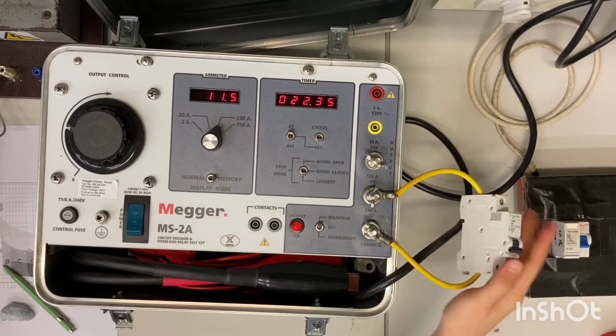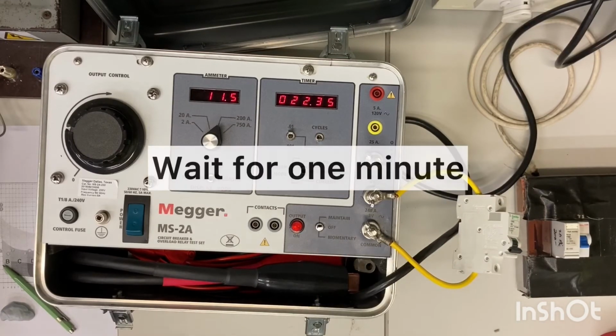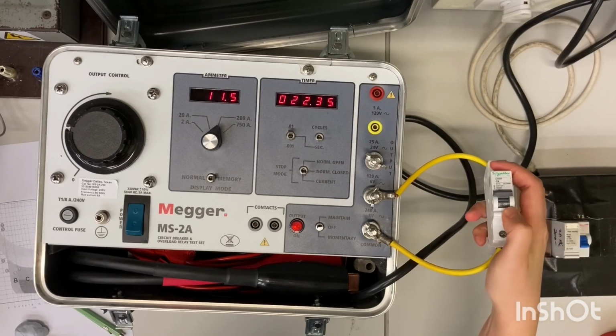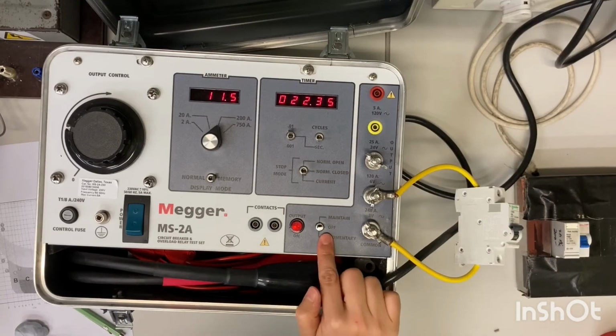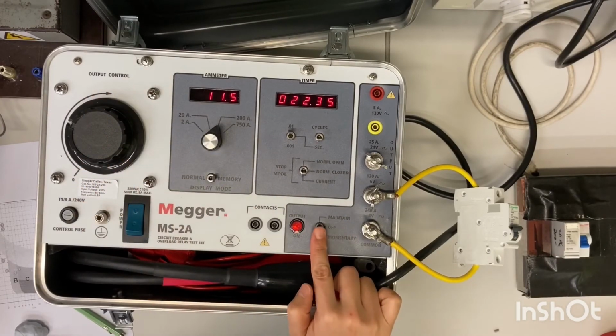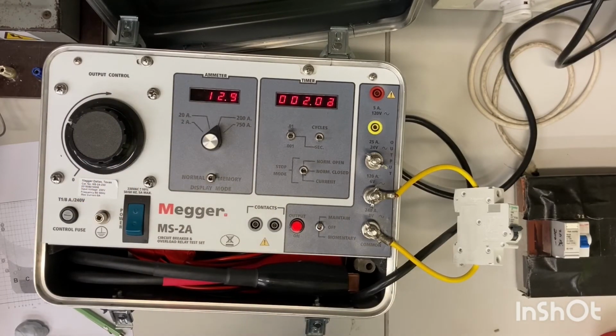So we just heard the click sound. The MCB is tripped back to the off position, and wait for 1 minute for the MCB to cool down. And after 1 minute, we can just repeat the procedures for larger current values, just like what we have done for the type B MCB.